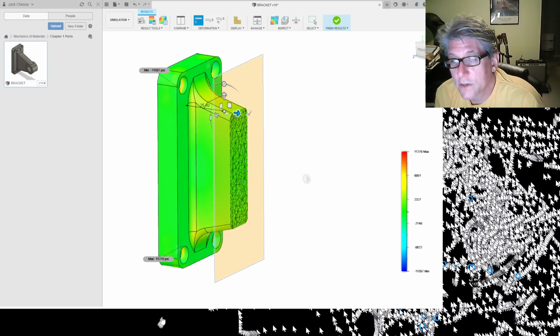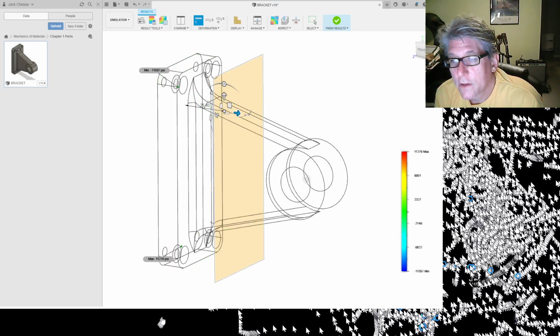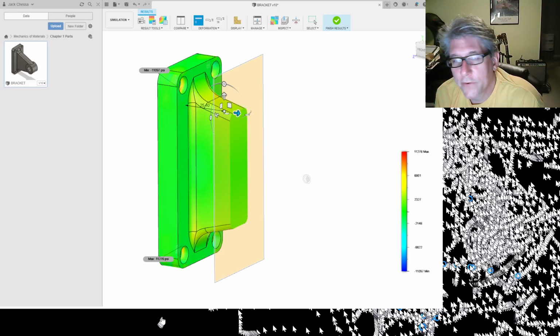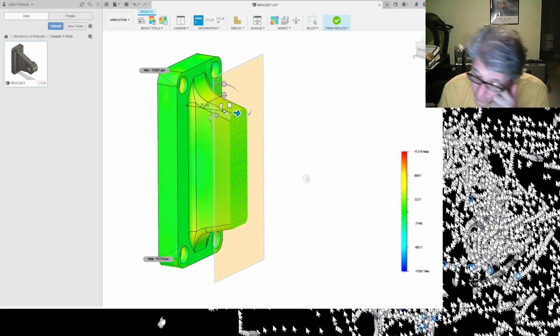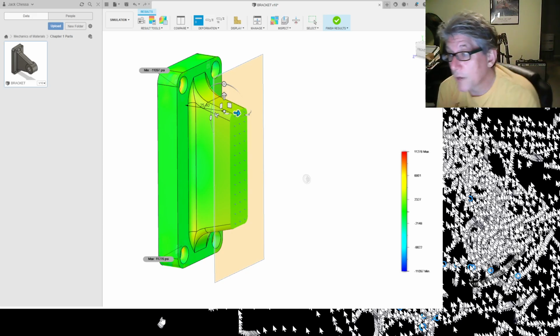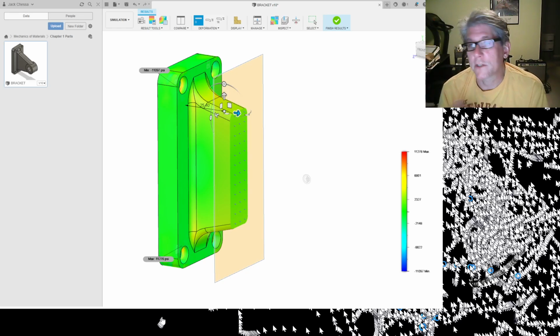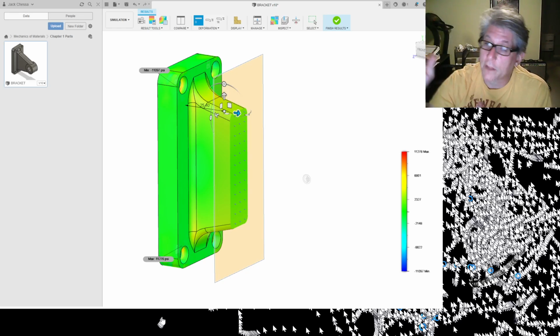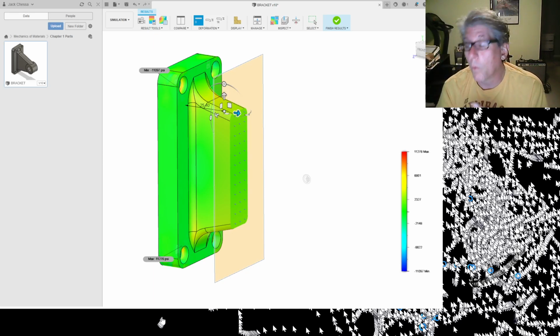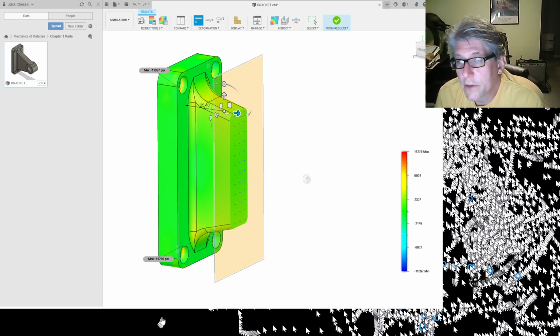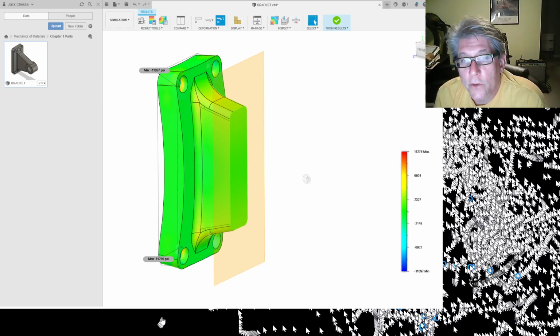You can change like what it looks like on the cut surface. Sometimes it's a little confusing, you know. So, okay. Whoops. Wait, what is that doing? That's weird. Okay, so that one's not too bad. This one shows the traction vectors on there, okay? And here you can see the normal traction vectors are all in the X direction. There's no shear, right? If we were to load it like in the Y direction, you'd actually see shear tractions out there, okay? You know, you can leave those on or off if you want to. But, okay. Fine. So now you can see the stresses on here. It's pretty uniform, okay?